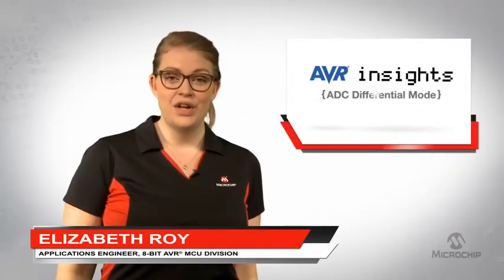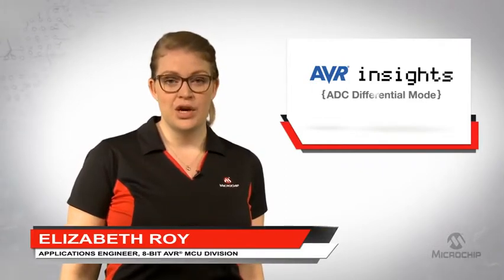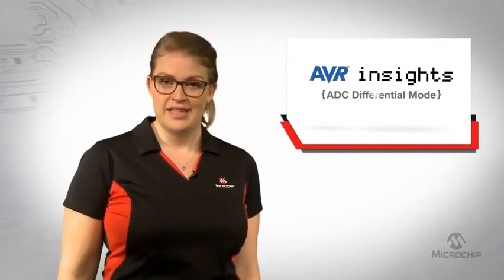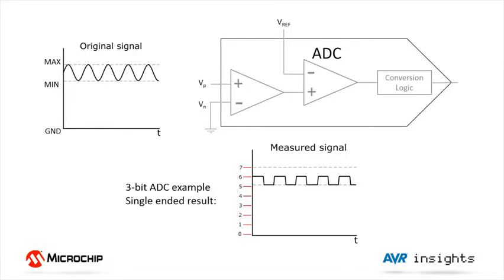Hi! In this video we'll look at the differential measurement feature of the AVR ADC, when to use it and how it can be used to calibrate the ADC. In normal single-ended mode, only one pin is used for the ADC measurement. The resulting ADC conversion value will reflect the signal applied relative to the device's ground value. This means that a signal will always be measured somewhere between ground and the ADC reference.